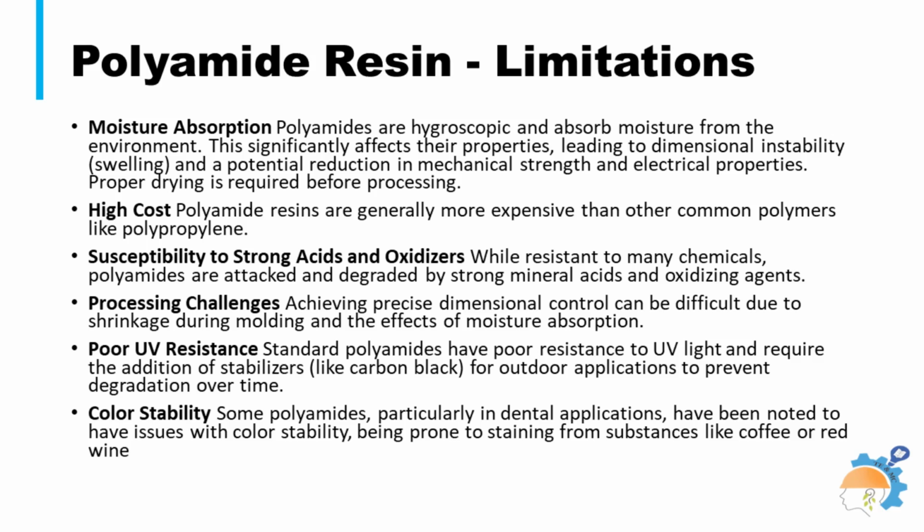Despite their numerous advantages, polyamides have some drawbacks that must be managed for specific applications. Achieving precise dimensional control can be difficult due to shrinkage during molding and the effects of moisture absorption. Some polyamides, particularly in dental applications, have been noted to have issues with color stability, being prone to staining from substances like coffee.